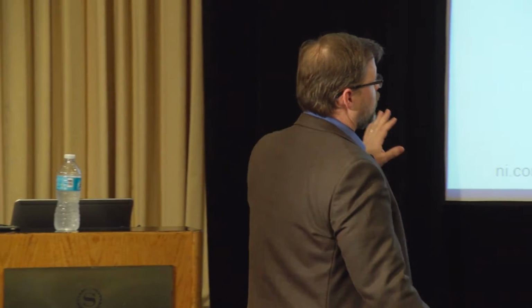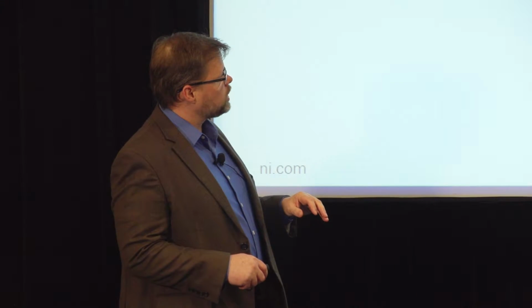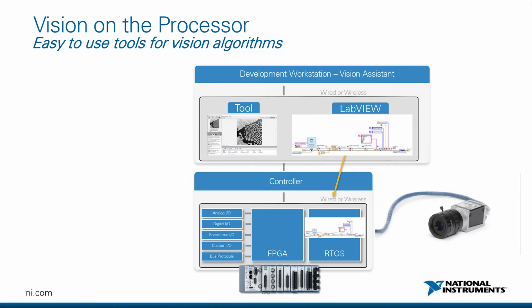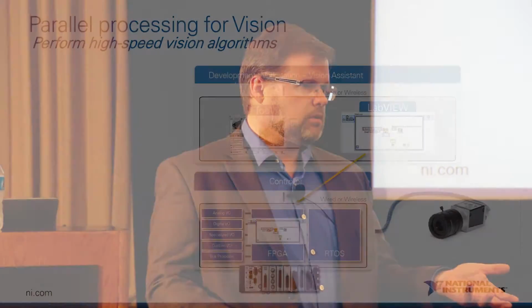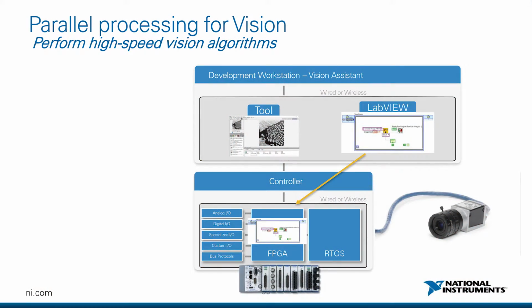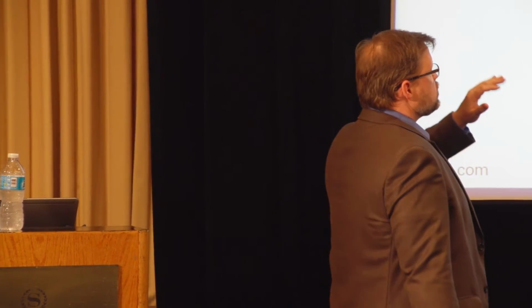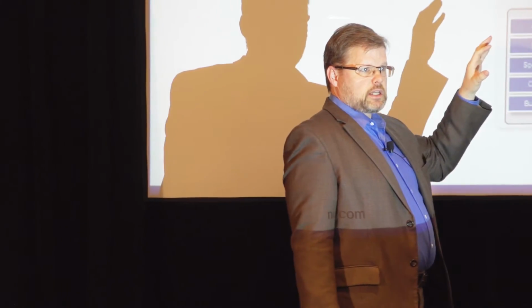So here's an example of a fundamental system where we have a camera hooked up to a real-time operating system that's doing image processing. The particular image that we're going to be looking at is molten metal, looking at the properties of the metal. Just as you see the picture, that's what it is. I don't want you guys going, what is that picture? That's what this is. Okay, so you can, of course, do this blob analysis, as it's called, which is a binary form of image processing, using a processor-only system. And that's the way a lot of it's done.